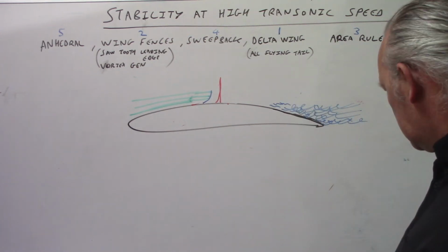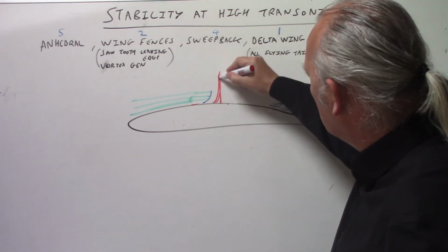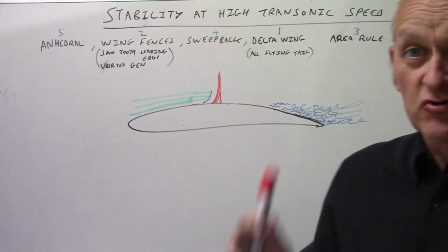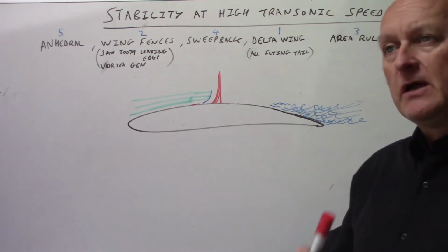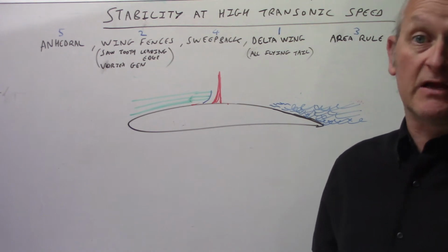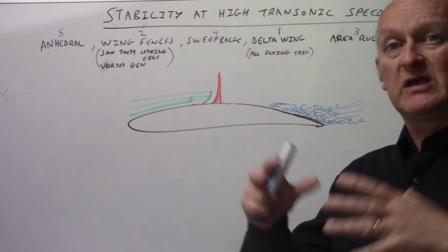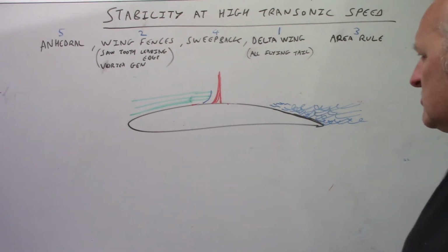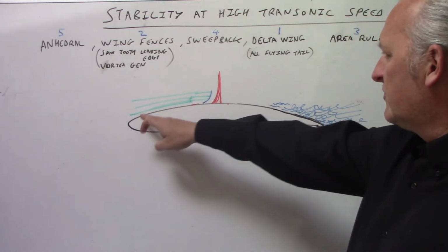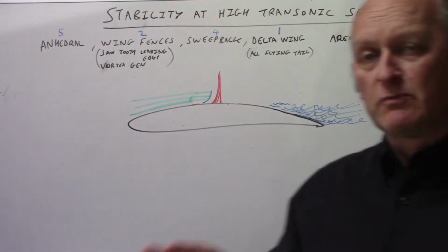As that creeps up towards there, and as this shockwave gets a little bit bigger, we'll make it a slightly bigger shockwave on a standard subsonic cambered aerofoil, on something like a Jet Provost. If you're trying to stick a very cambered wing, which creates lift, through the sound barrier, like a glider wing, up to about Mach 0.7, you'd get a big shockwave formed on it. The shockwave won't form at the front; it will form around about here, at the point of maximum camber of the wing.